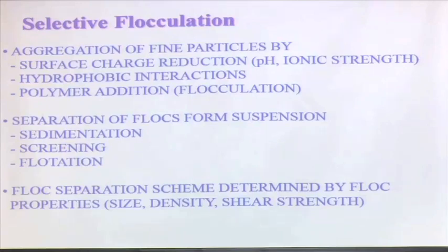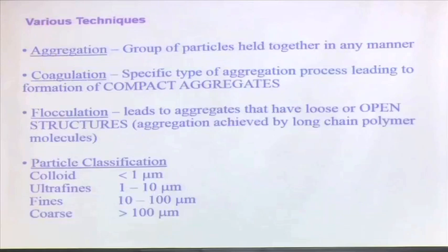Okay. So, the floc separation scheme is determined by floc properties, that is size, density, shear strength. The characteristic of the floc I have will determine which method we will use. So, various techniques we name distinguish the different techniques.